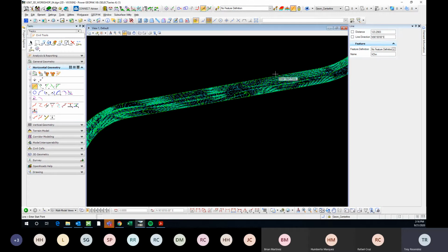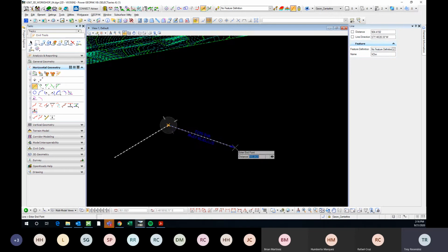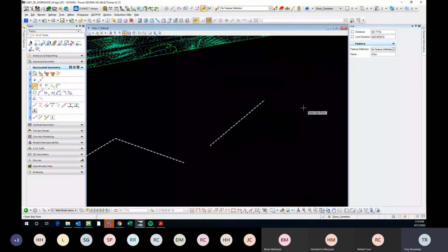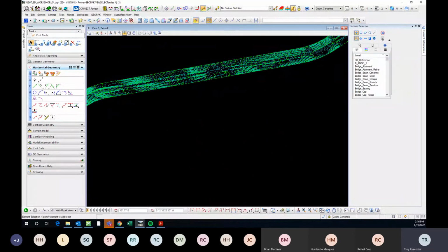And once you have this on, it basically means when I click and create a line, it's not going to end the command. It's going to keep it going, right? So if I turn it off, then if I click again, it stops.